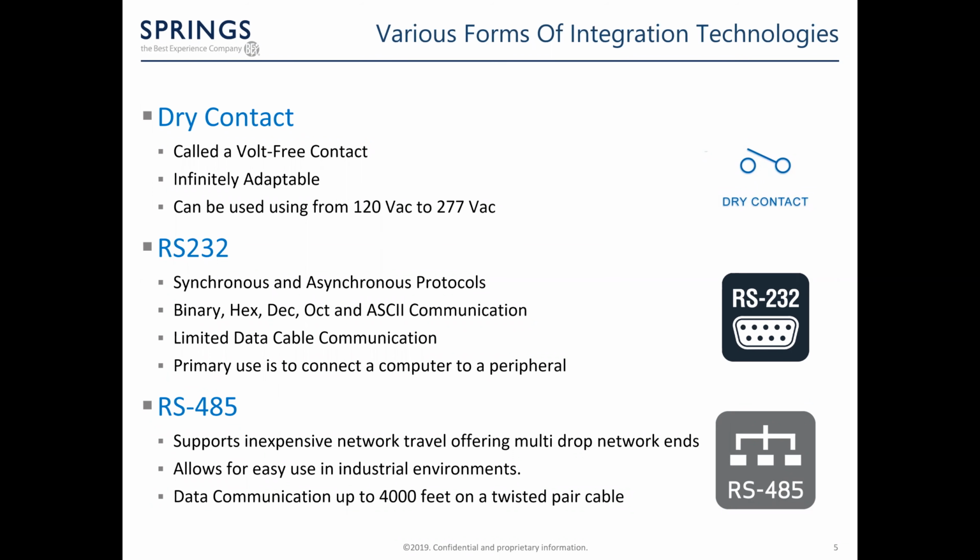Asynchronous communication has no timing signal or clock. Instead, it has start-stop bits in each byte of data to synchronize the communication. It also uses less wire for communication with no clock signals. Asynchronous communication is simpler and more cost-effective. RS-232, RS-485, RS-422, and TTL are forms of asynchronous communication. It also communicates at speeds from 100 to 220K baud.